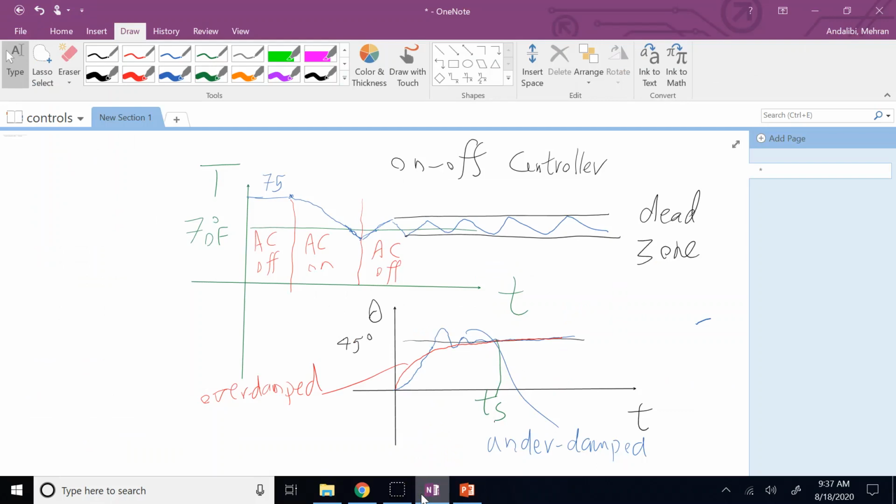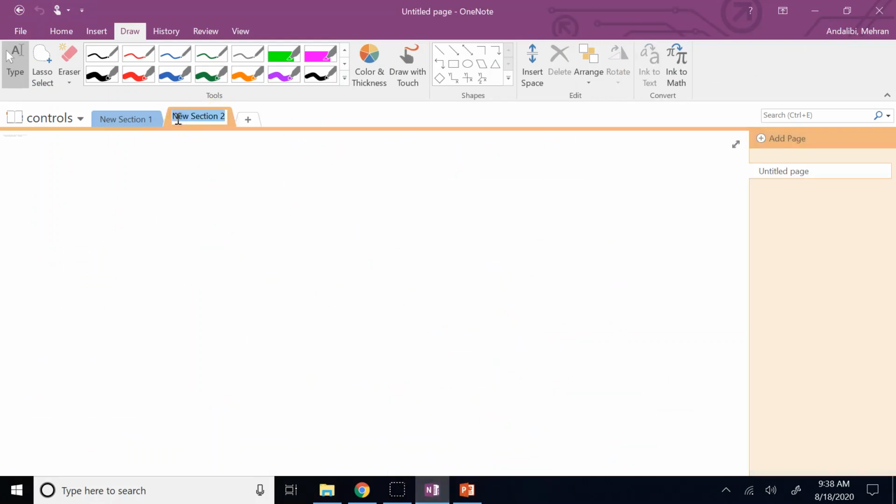So you know from your statics or dynamics course that if you have an axis, and a mass m, and the distance of the mass to the axis is called d, then the moment of inertia, J, of the mass with respect to the axis is calculated by what? M times d squared if it's a point mass, yes? So the bigger d, the bigger J.